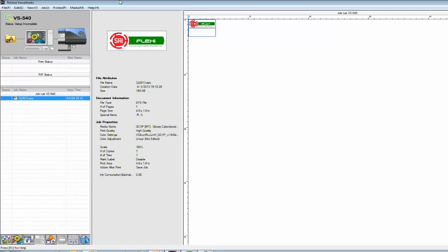For the basic queue setup, most of our clients set up the QA for your standard print-cut option using their most common vinyl products. And in order to start changing some of these settings, we go to the edit menu, and here again you can change your QA settings, QB settings, and so forth. QB normally, at least for the clients that we have, is set up either for banners or an additional product that they use quite a bit, or set up as a cut-only option.